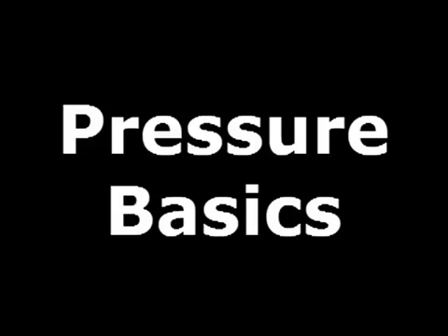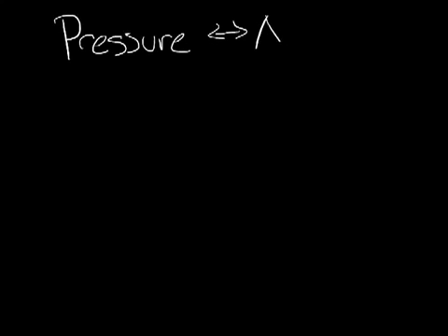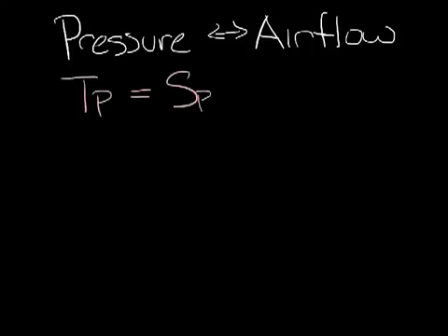Today's topic is pressure. You can't talk about HVAC systems without discussing pressure. There's a relationship between pressure and airflow, and you need to know airflow to make everyone comfortable in HVAC systems, so it's pretty important. Let's start with the pressure equation. Total pressure equals static pressure plus velocity pressure.